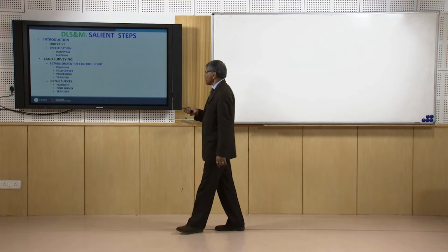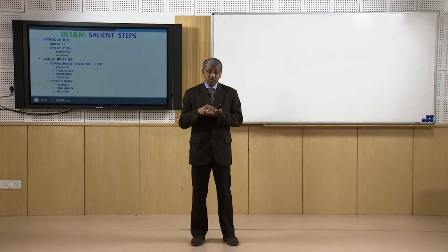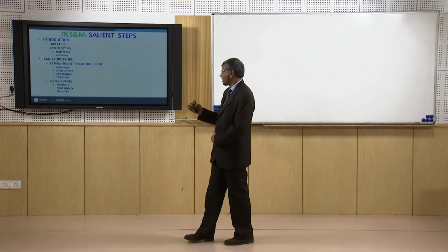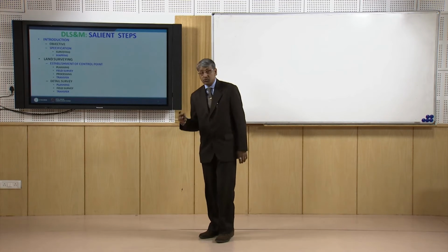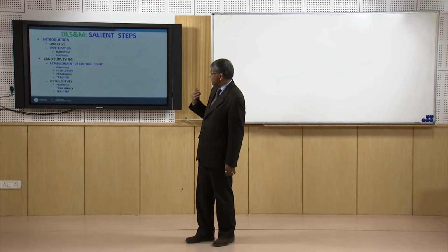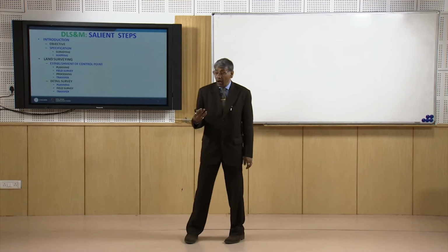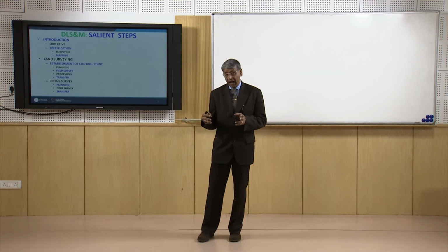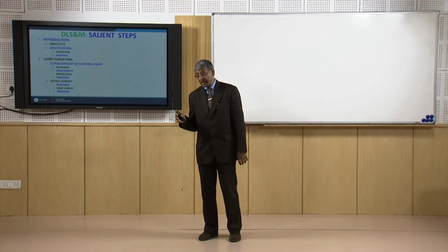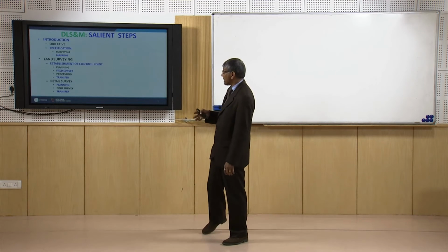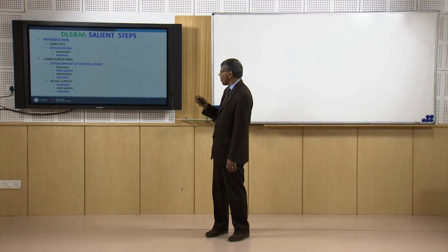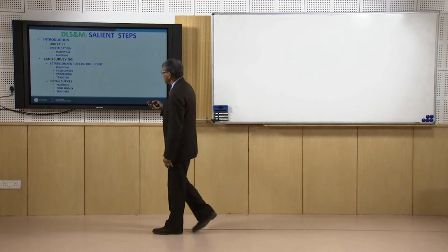So in case of a building project, we will need contours at a very close interval, that means the difference in height between two consecutive contours should be small. For that type of contouring, we will need a lot of spot heights and height data of the study area, and as the number of points whose height has to be taken increases, more points will be involved in mapping.